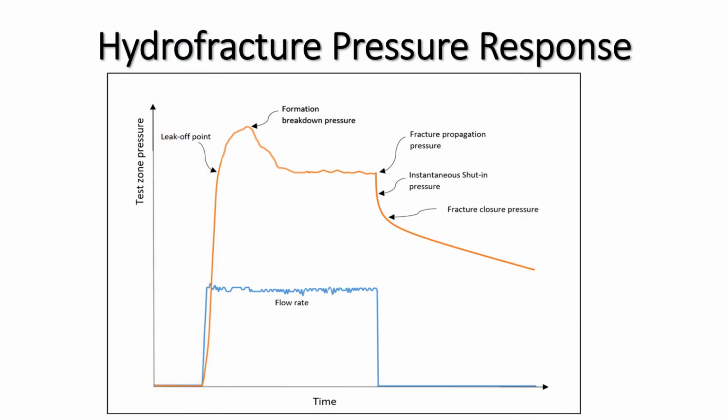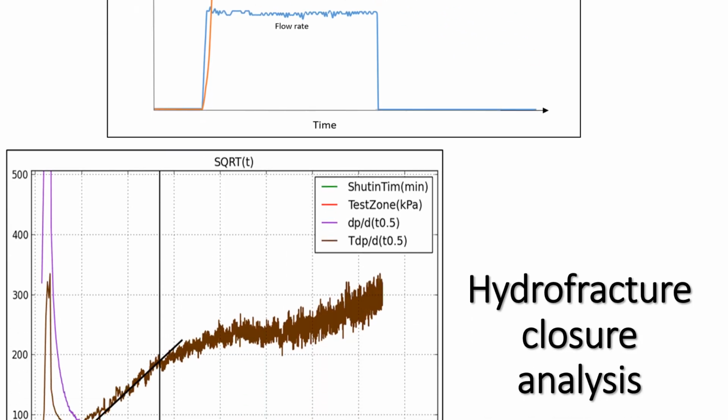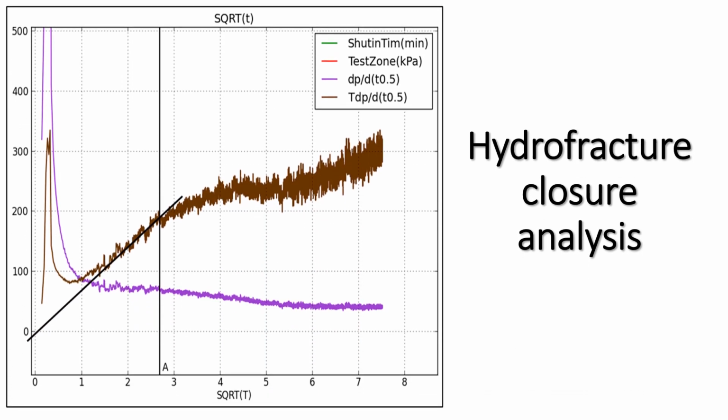The measurement of rock stress through hydrofracture requires sealing a section of the hole and pressurizing it until a fracture is created in the borehole wall, then propagates. Fluid injection is then stopped and pressure decline takes place and the fracture closes. The process is normally repeated by pumping again and reopening the fracture. The normal analysis of hydrofracture is based upon measuring the closure pressure of the fracture as an indication of the minimum stress level. This is determined by careful analysis of the pressure decline after pumping ceases.